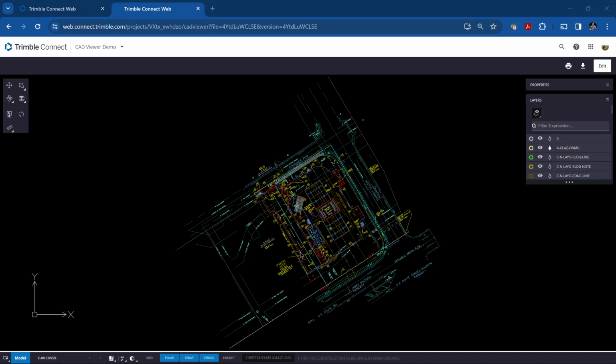So in this video, we'll take a look at some of the measuring tools for measuring distances and areas and even coordinates. So again, we're just in the kind of view mode, and over in the upper left on the panel, you've got this inquiry tool. It looks like a ruler. If I select that, you'll see that I can choose distance, area by entity, area by point, or coordinates. Let's start with distance. So I'm going to click on the distance command.